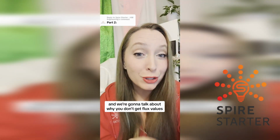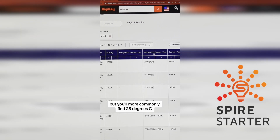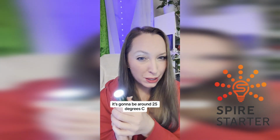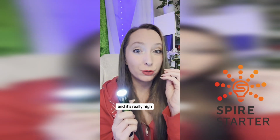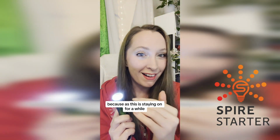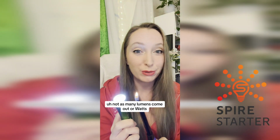Part 2 of LED datasheets, and we're going to talk about why you don't get flux values, so lumens usually, for 85 degrees C from different vendors for LEDs. But you'll more commonly find 25 degrees C. Why is that? It's because when you first turn an LED on, it's going to be around 25 degrees C, and most manufacturers will take a measurement right then of how many lumens are coming out. And it's really high because as this is staying on for a while, it will warm up. And as it warms up, not as many lumens come out, or watts.